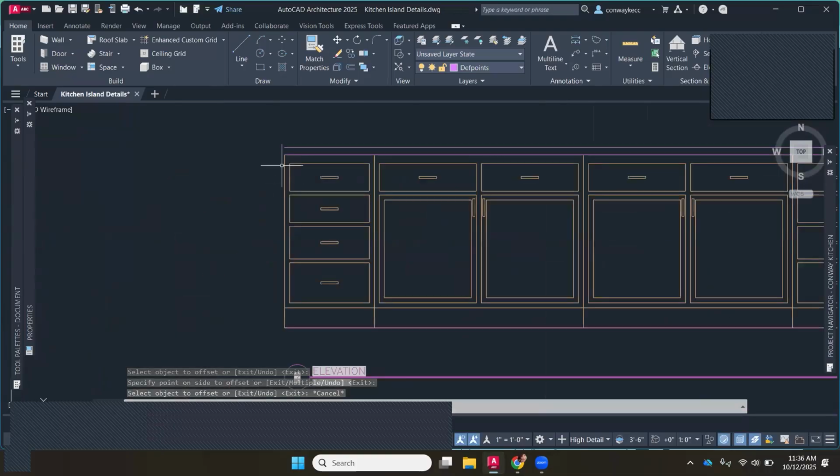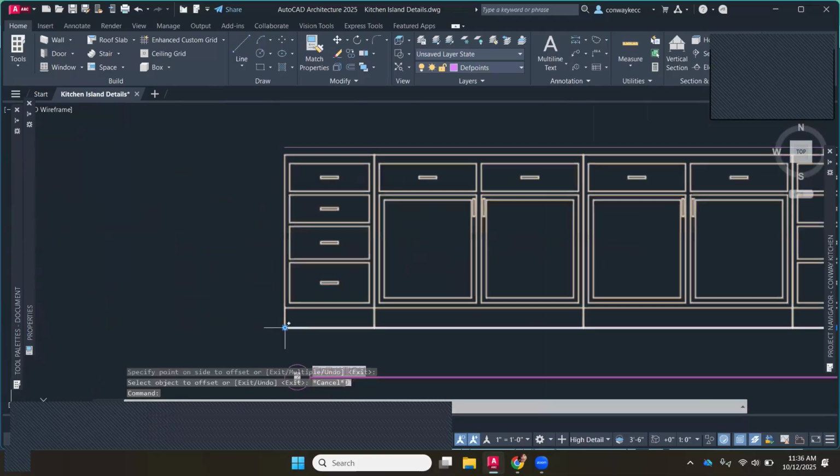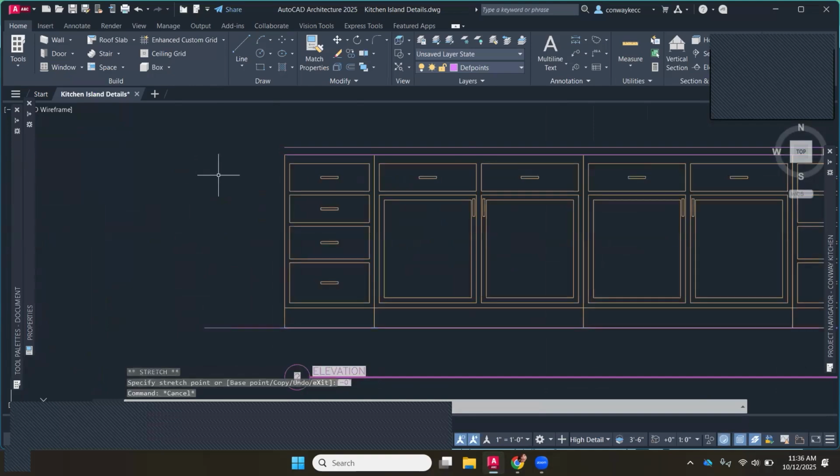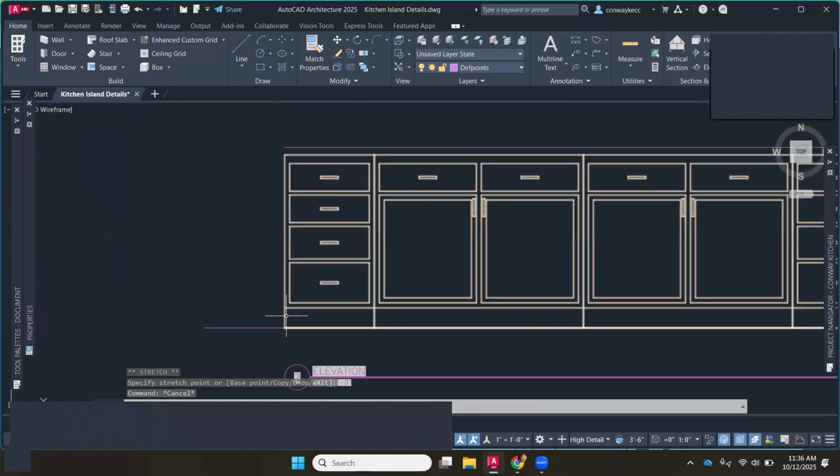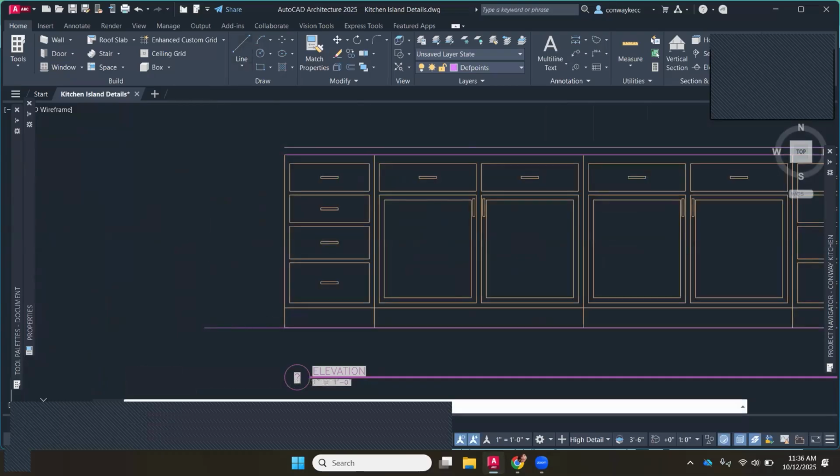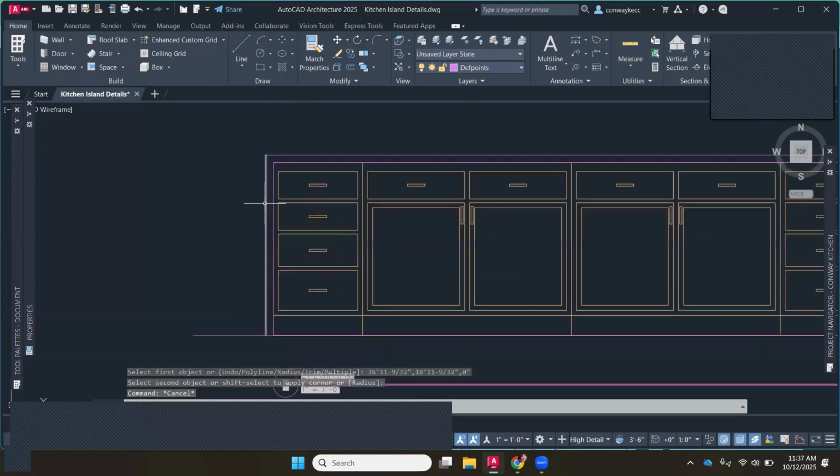So here's where you start to decide. If you have a waterfall edge here, let me pull this line up. What you're going to do is trace this line and then offset it to the left 1.5 inches. So I can show you that quick so you can see what that looks like. All right. Oops. Somehow I started at the wrong spot there. Let's go here. We're zooming there. Okay, we're offsetting 1.5 inches to the left. All right. And then if I use the fillet command here, we're going to do, oops, let's rotate there, there and there. And see, now I have, that would be my waterfall edge on the left if I wanted to do that.